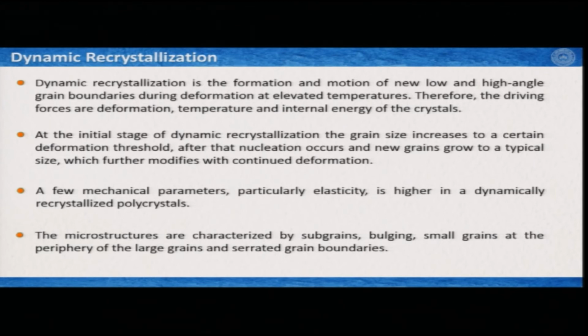If we think of the mechanical parameters, then particularly elasticity is higher in dynamically recrystallized polycrystals. And the microstructures are characterized by subgrains, bulging, small grains at the periphery of the larger grains, and of course serrated grain boundaries. Now, we will learn about all these things, the subgrains, bulging, small grains at the periphery of the large grains and serrated grain boundaries, in the following slides.